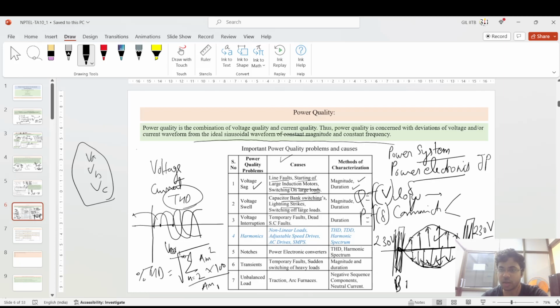That's why in the fast decoupled method, we take del P del delta and del Q del V. By that we define which components are more related to the particular terms.